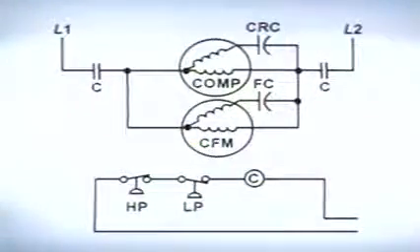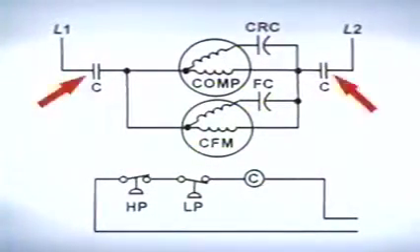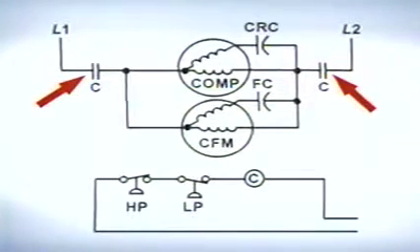In this schematic diagram of a small residential air conditioning system, the two sets of contactor contacts are used to energize both a compressor and a condenser fan motor. In larger systems, each compressor or fan motor may very well be controlled by its own contactor.